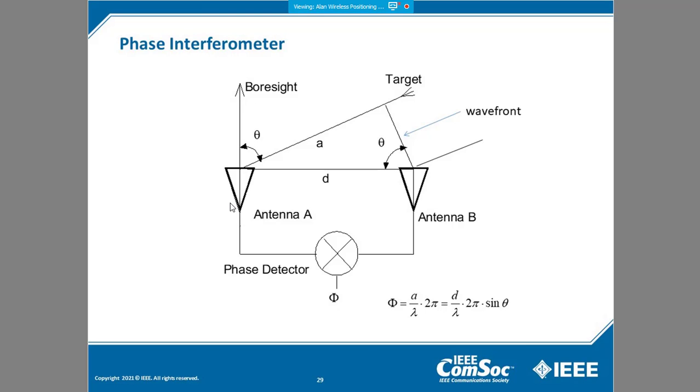at the two different antenna elements, and at the wavefront, the phase of the signal. In other words, we assume that the target is far enough away that the distance to this point on this wavefront is the same. Obviously, this distance will be the same if the target is very far away. In real life this would be a semicircle, but very close to a straight line, and the phase would be the same on all points of this wavefront.